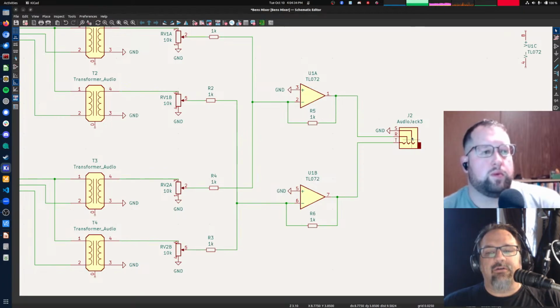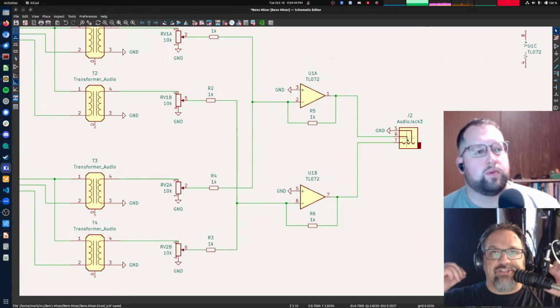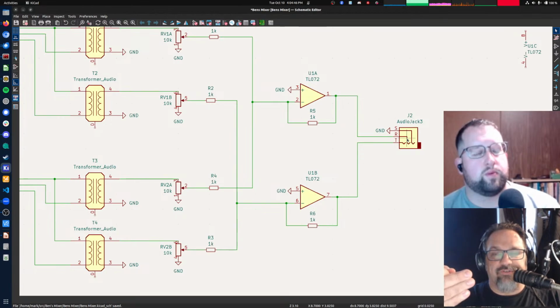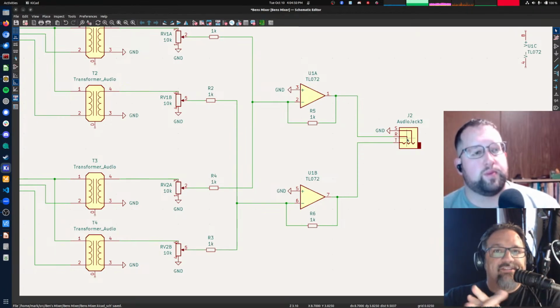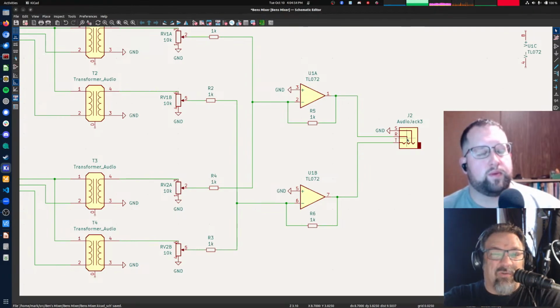So neither of these are going to headphones directly. Is that right? You're not trying to drive a speaker with these. These are just line level outputs. One's going to a Bluetooth transmitter and the other one's going to a powered amplifier, right? Yes. Okay. So those loads will be at lowest 600 ohms, probably closer to 1K or 10K.